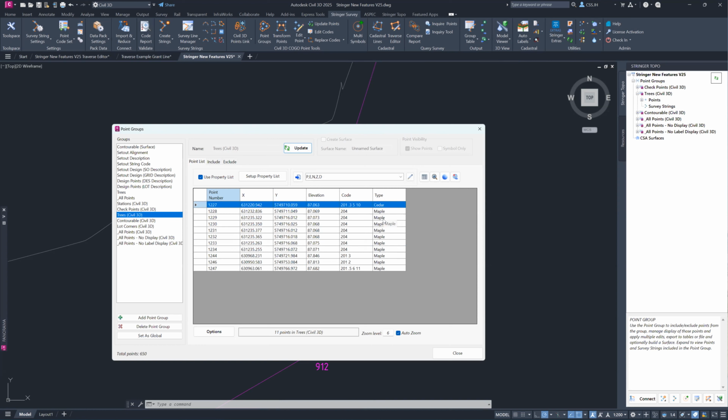Now you can work with this in a variety of different ways. You're able to export it and import it in other areas as needed. If we wanted, we can export it out as a CSV file, just add on the extra property and you're able to export it out as a CSV or text. You are able to set it out as a CAD table, a KML, if anyone here uses Google Earth, can be a very powerful tool for using it. But the last one we're able to export out is the Esri shapefile format. Now, the Esri shapefile format allows you to export out the line work and the points as separate files.